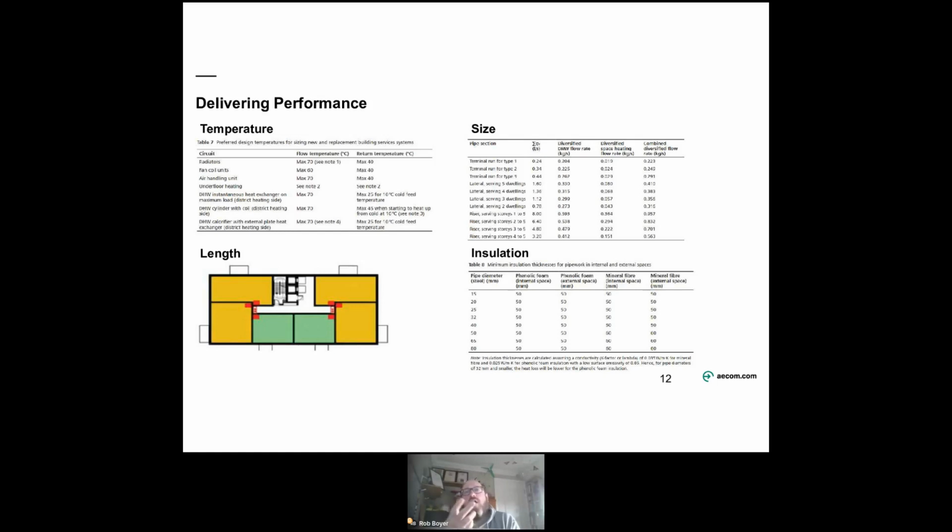Within CP1, there's an illustration of how HIUs can be placed nearer to risers. So we're almost designing them more like soil vent piping systems, because it is the laterals and terminal runs that really have the biggest impact on length, total installed length within a residential development. There's also guidance on sizing, both in diversity analysis, velocity sizing of pipework, and there's a really good worked example within CP1 under Annex D, if you want to follow through how that would actually work.